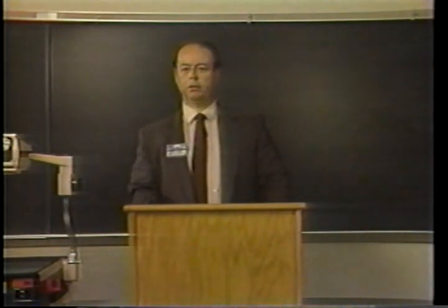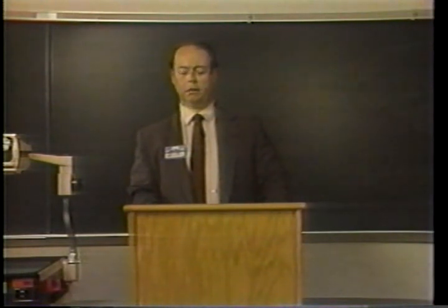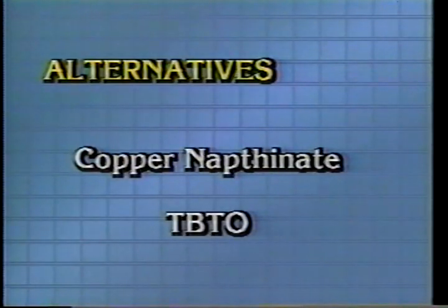There are some alternative preservative systems which may be used. These can be used in field cut areas, but they are not used in terms of pressure treatment. These alternative preservatives would include copper naphthenate, TBTO, tributyl tin oxide.